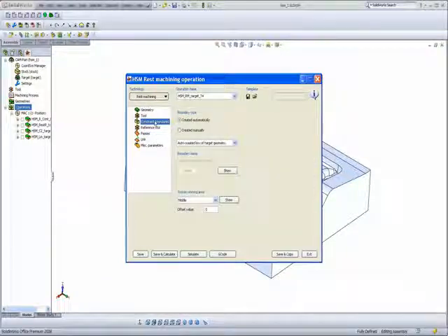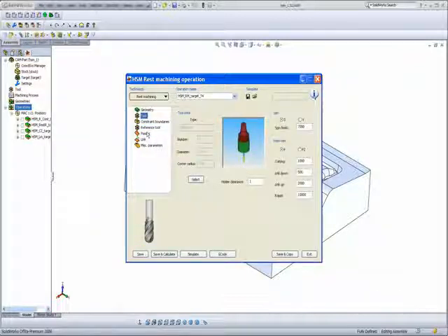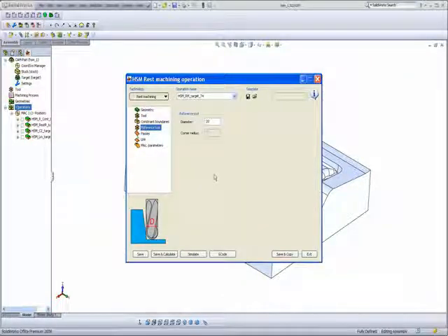Again, I have my constraint boundaries, but we have something else here now called reference tool. With reference tool, I can tell this particular tool that I'm working with now, the 6mm ball end mill, which areas to consider as not machined. I can tell it wherever, for example, a 12mm ball end mill was not able to go in, those are the areas that you'll be working in. Now I picked 12mm, even though before I used a 10mm tool, to have a little bit of an overlap of those areas that were not able to be machined.